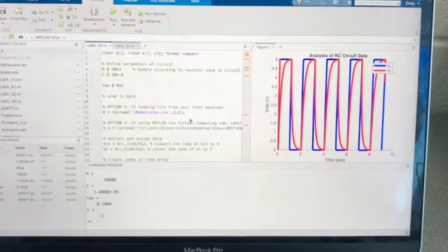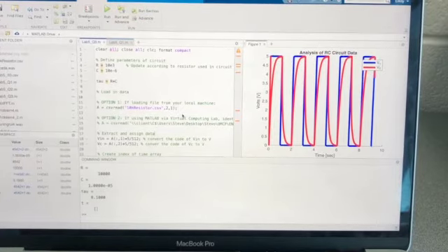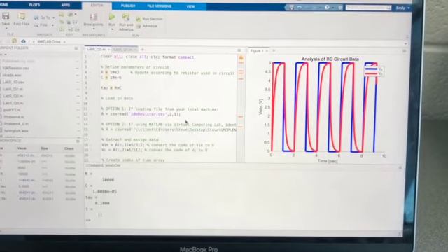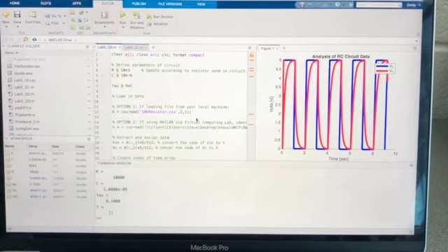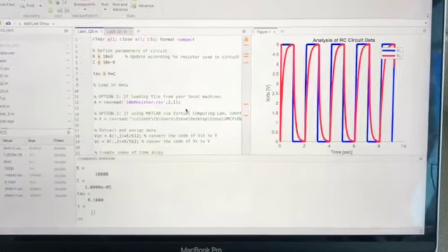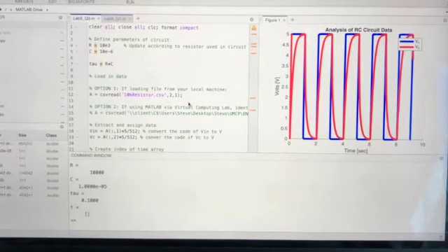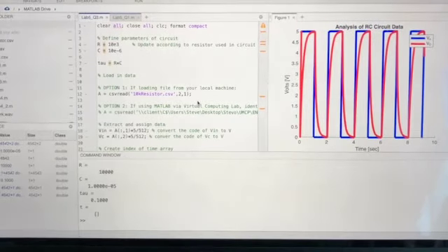In my MATLAB code, I changed 3 things. The CSV file name, I converted the code to voltage, and then I also changed the y-axis data label. As you can see from this graph, Vc gradually increases charge to 5 volts, then gradually loses it when 0 volts is applied.